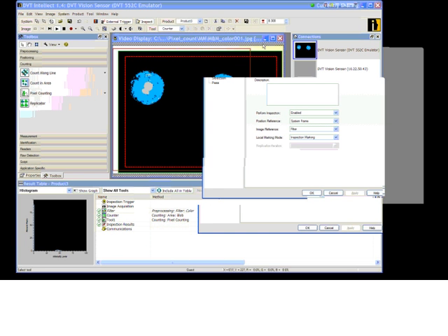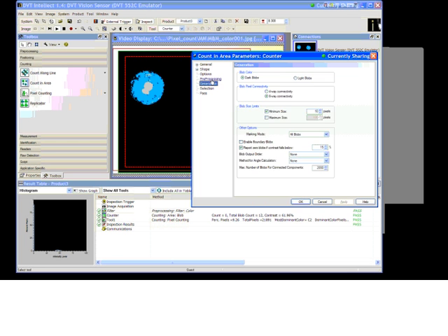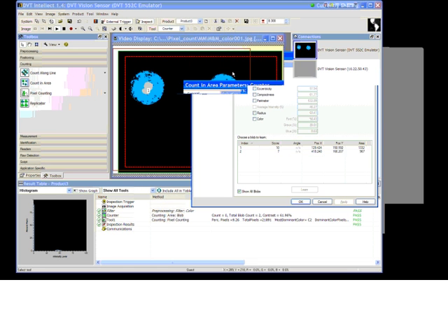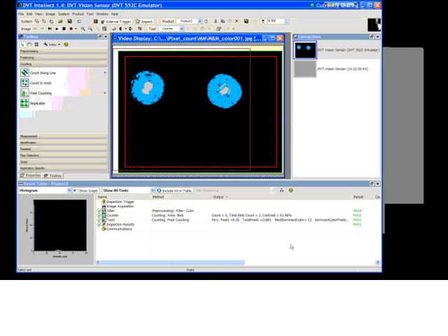And now the blob tool is counting a few blobs, and we can do some morphological operations to include some of that, or expand and dilate the blobs. We can increase the minimum size, say to 500. In that case, we only get the main two. Go to our selection tab, we see the two numbers. So now we're counting 2 blobs. So this is a way to share the colored information from one tool to the next.